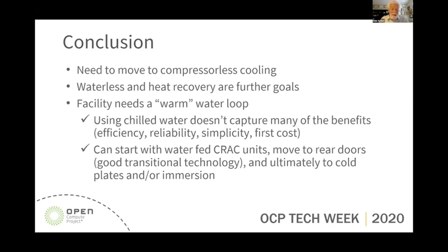As I mentioned, for us, the benefit of not having a chiller plant is efficiency, reliability in terms of reduced number of components, simplicity, and a lower first cost. You can start with a water-fed CRAC unit. That's what we have. Once you've got that loop of, say, tower water or dry cooling, the water-fed CRAC units can easily run on that. So that's a conventional system.